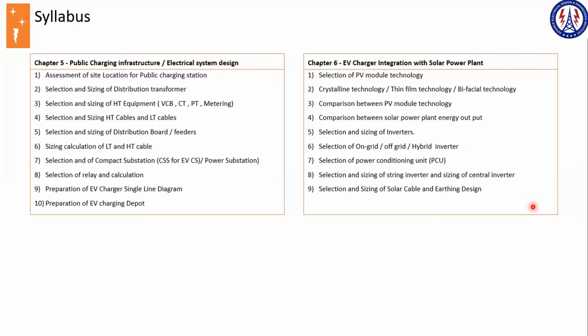Which is very keen to understand, because if I look at the building parts, they are dealing with small cables, right? 4 square mm, 10 square mm, 16 square mm. And very few lengths of cable are required for a larger size, like 120 is good enough, right? But in EV, a single charger will take a 120, right? And then we need to deal with the larger one. So how to handle that part?